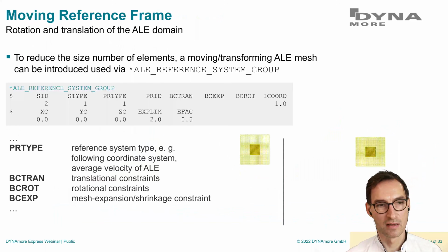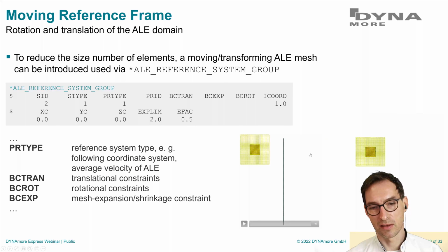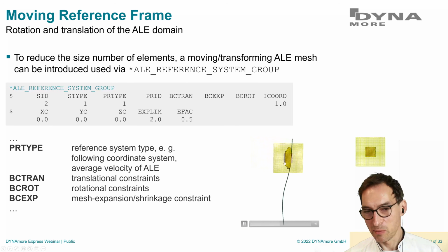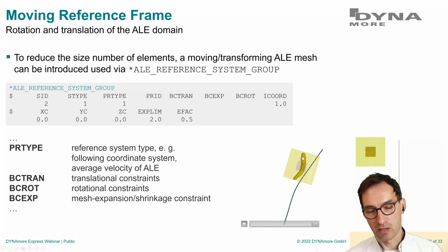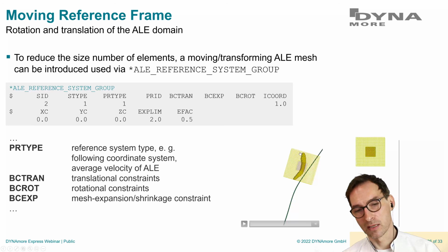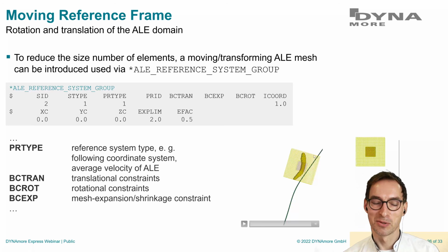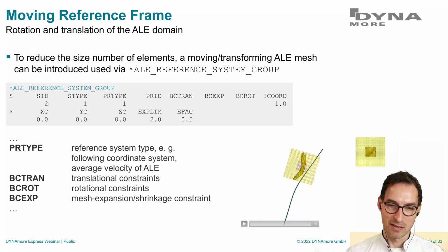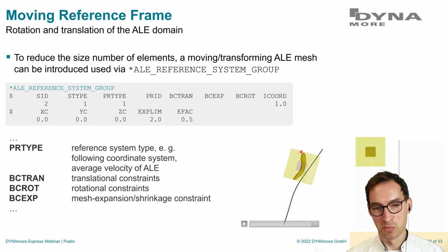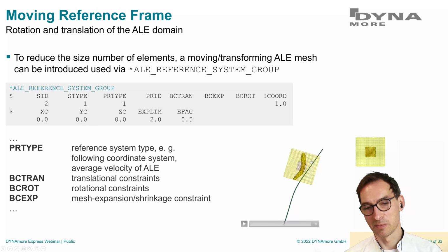So for instance, here in this one, I think it was a nice example. We have here the bird-like material. We're lucky because the material doesn't reach the border, but actually here we have an outflow boundary condition. If I want to keep it inside of this one, I have to prescribe, that's a good question, how I do it in this case. I have to somehow fix the displacement here, and hopefully in this particular case, LS-DYNA moves it with the boundary.